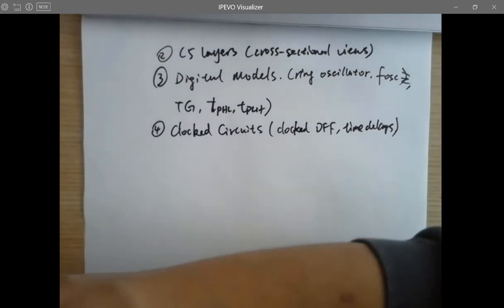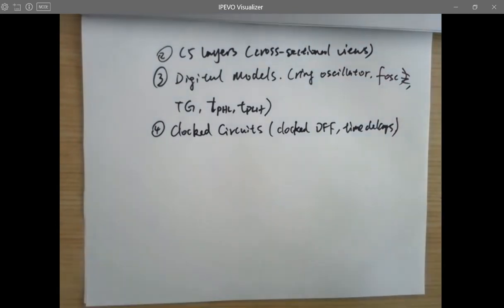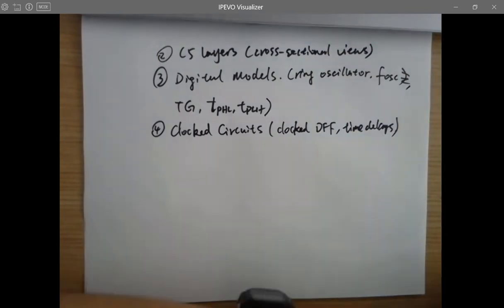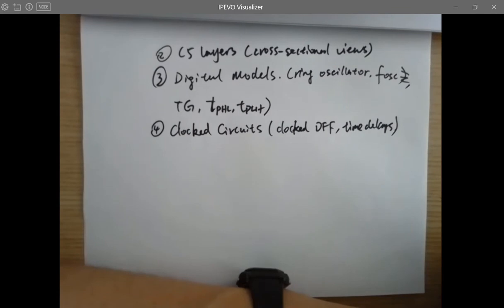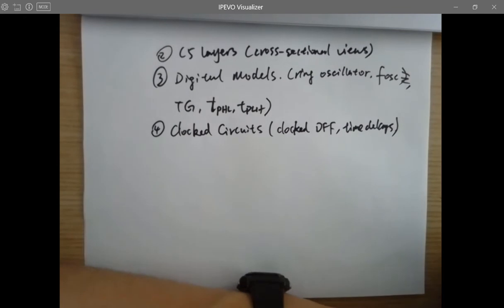Just keep in mind, if I just keep the transmission gate in one state, when I'm looking at the time delays, you cannot have the transmission gate to be both on and off, right? It's either on or off for some of the transmission gates. And you are not including any of the time delays from the off transmission gates. So just ignore them. So only the ones involved in the transmission. So the gates have to be on.